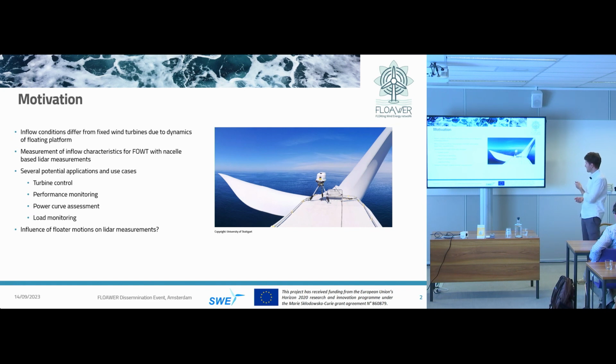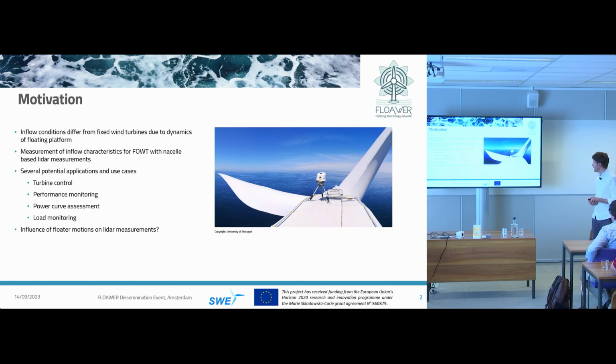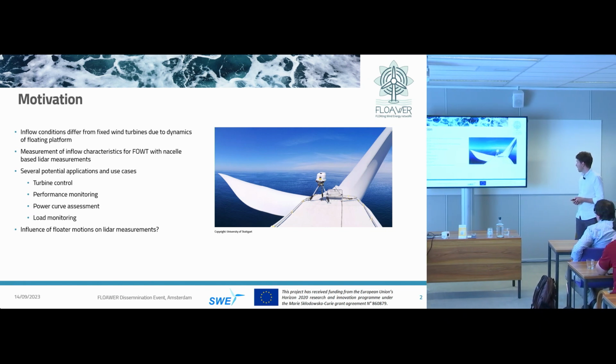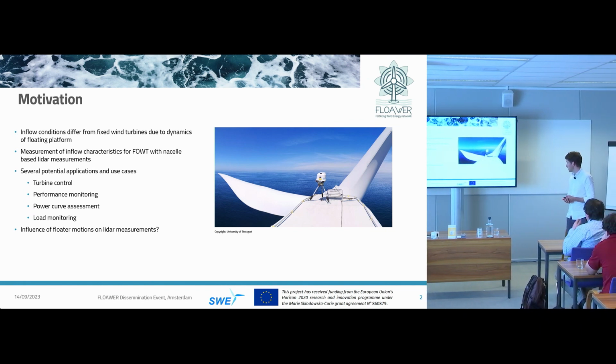So I'm talking about this setup, which you can see in the nice picture. This is the Ideol FlowGen demonstrator wind turbine in Brittany, and we, from University of Stuttgart, have installed our nacelle lidar on this turbine. In this setup, I'm talking about inflow measurements, so the lidar is looking forward into the wind field. Just as a side note, this lidar is turned around, and we are doing a wake measurement campaign also